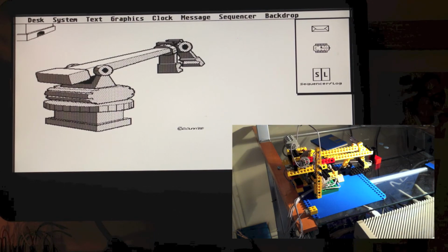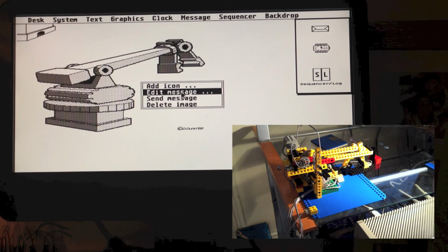As you can see, using the time isn't really an accurate way of being able to control a robot, because there's too many factors. Really what you want to do is bind the motor to an encoder, and you want to detect a number of pulses that that encoder receives to then determine what position that motor is in. But for the time being, we'll use the motor time just to give you a feel for how this works.